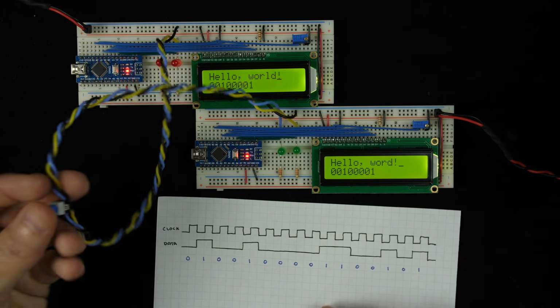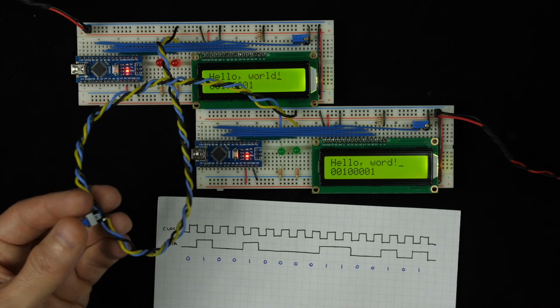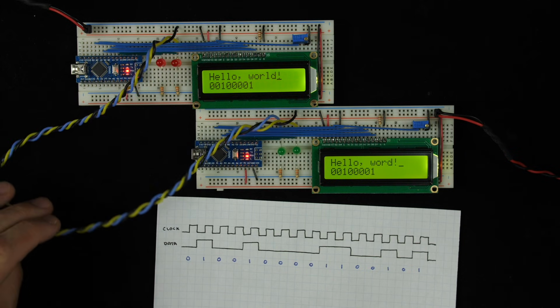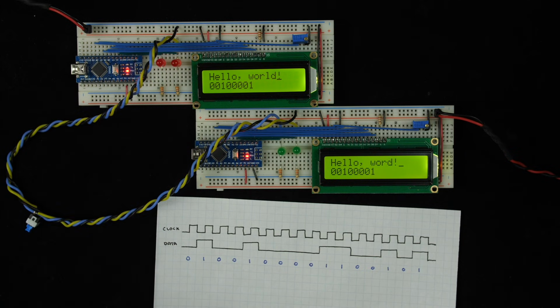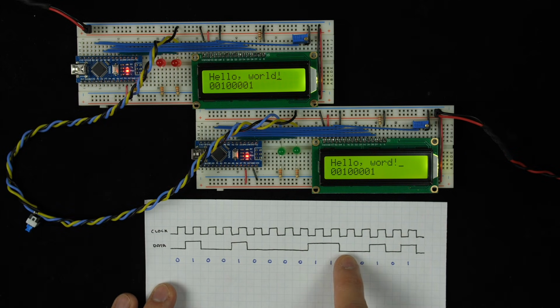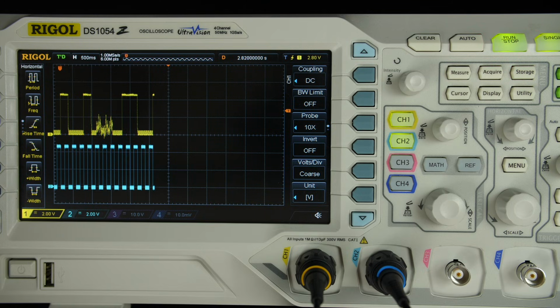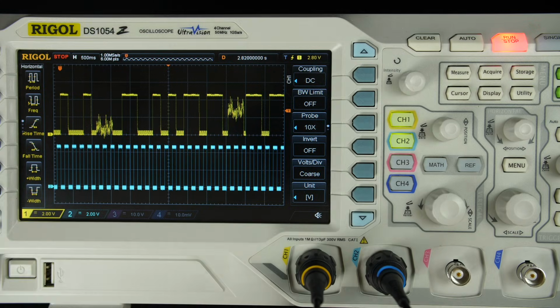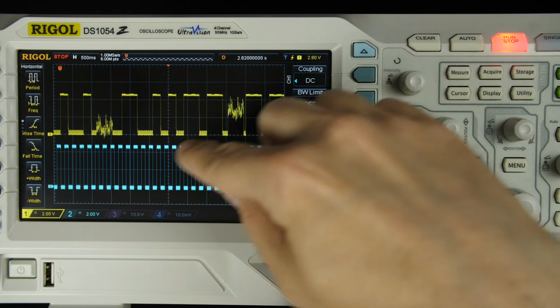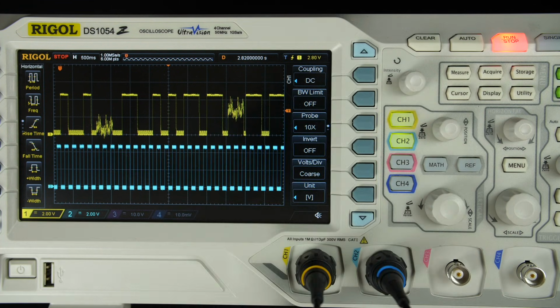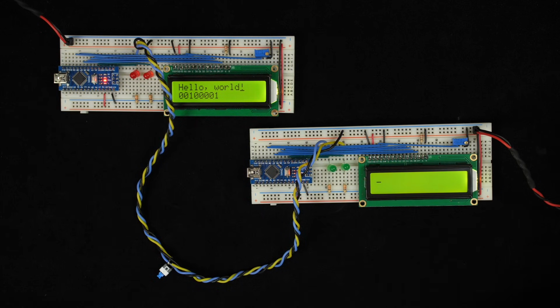So now I know I'm using this switch to artificially cause problems, but it's because it's possible for this sort of glitch to happen all on its own. So I'm showing these as nice, clean on-off signals, but really everything is analog. These are just voltages, and there's any number of reasons that occasionally this voltage might not be quite high enough to register as a 1, or this voltage might not be quite low enough to register as a 0. And without a lot of extra engineering work, any circuit's going to be susceptible to some sort of electromagnetic interference.